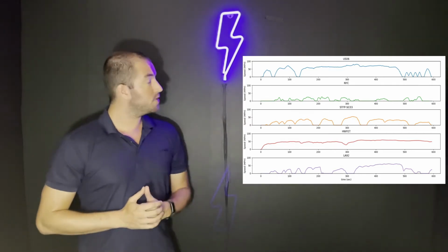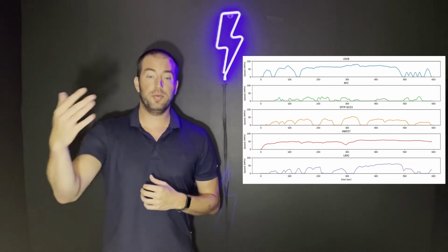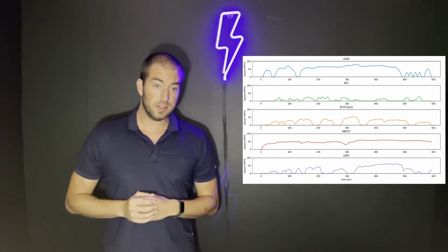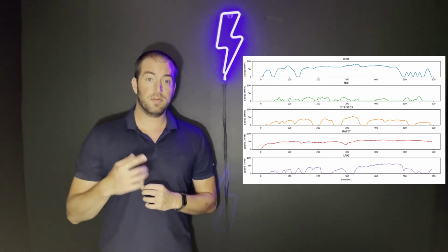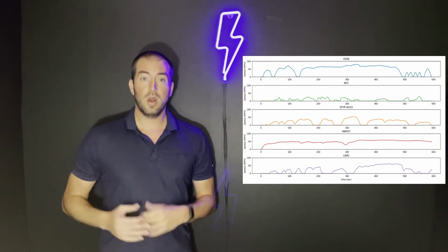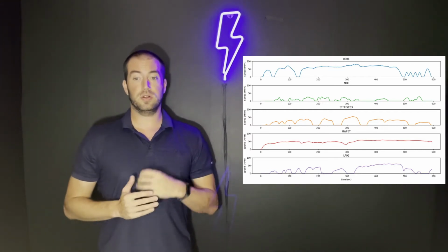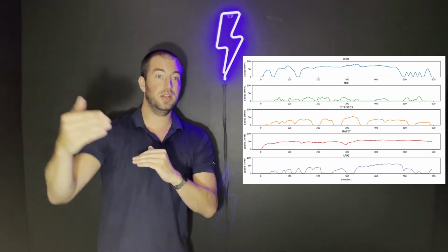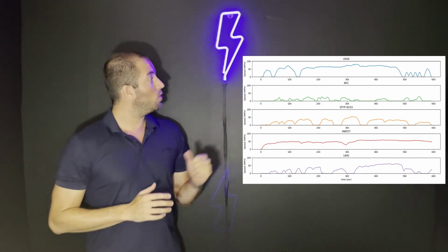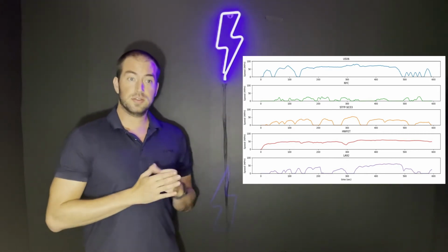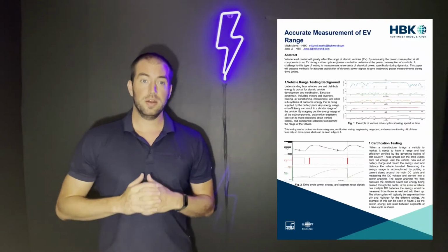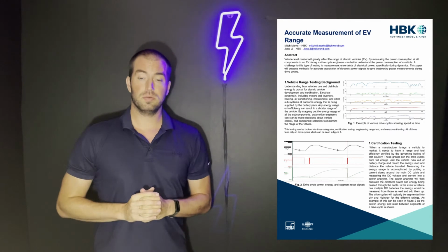If we take these drive cycles and calculate a 300 kilometer range, but we have a 1% measurement uncertainty, 1% of 300 is 3 kilometers, so we can only publish a 297 kilometer range. So by improving that measurement uncertainty, we can actually increase our range. That's really cool. So that's the drive cycles, these series of speeds versus time that we run the vehicle through.